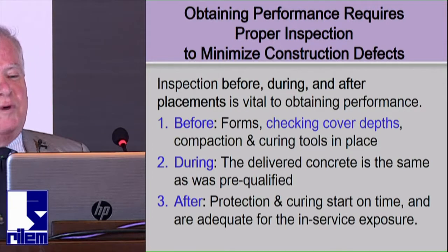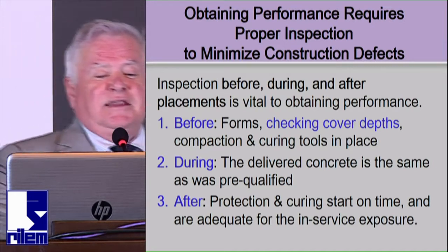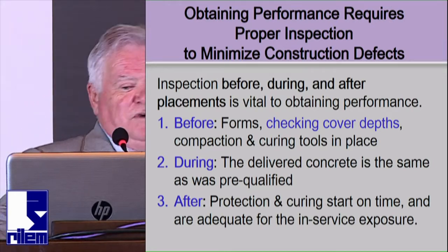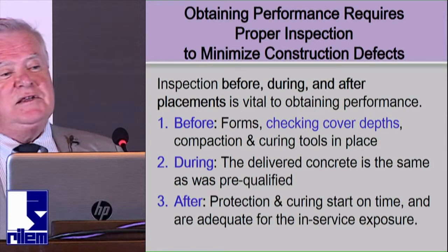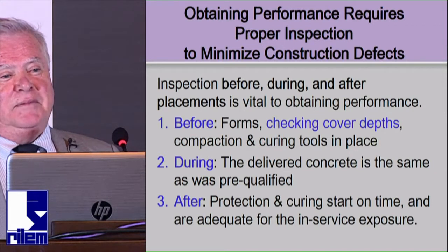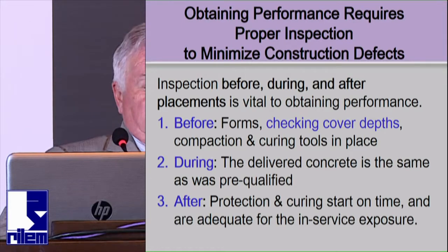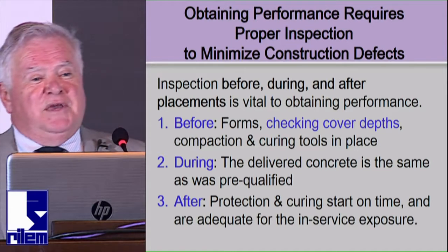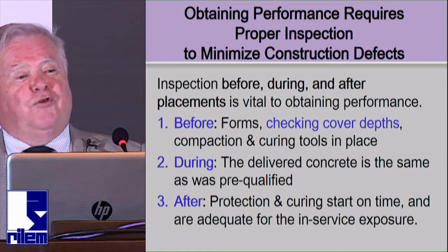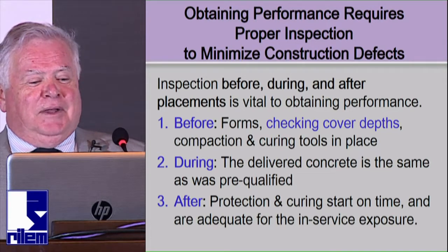And of course, you need to do proper inspection, because if you don't inspect, you're not going to get what you want. And that means inspecting before the construction. One of the biggest problems I see is cover depth. Nobody measures cover depth beforehand, or very few times, and that's where your biggest opportunity to extend service life is, making sure you have the achieved cover before you place the concrete around the bars.